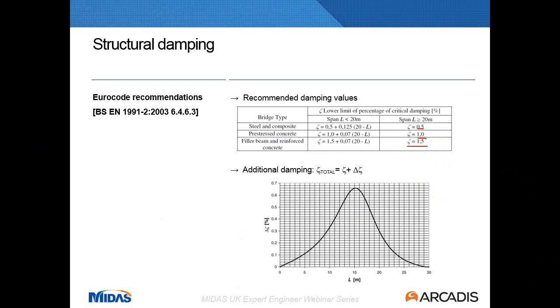My recommendation is for a specific structure, get your model ready, run just one train at one speed, and make sure that you're getting nice results. Do a sensitivity study, try to reduce, try to increase the time step, see if that has a relevant effect. When you're happy with it, then run the other route cases.